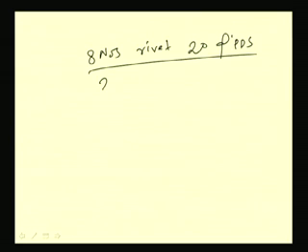8 numbers means if we use 2 rows, then 4 numbers of rivet in each row we can provide. So, from load point of view we can find out this much number. Now, let us see from the moment point of view. From moment point of view, how do I find out the number?